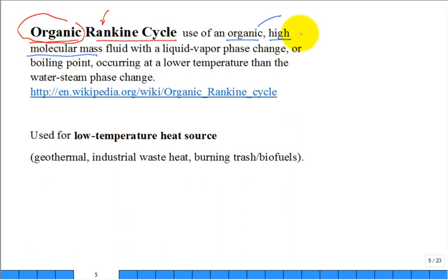You go back to like organic chemistry. Okay. So, what types of fluids might we use? Actually, refrigerants. They have typically some carbon in them, so they're organic fluids. You mean the refrigerants like we use in our air conditioning systems? Yeah, exactly. That's right. And why would you choose to move away from water, which has great properties, to a refrigerant, just so you could call it an organic Rankine cycle? Well, because it has different boiling point characteristics, different relationships between the temperature and the pressure in which it changes phase, where the dome sits.